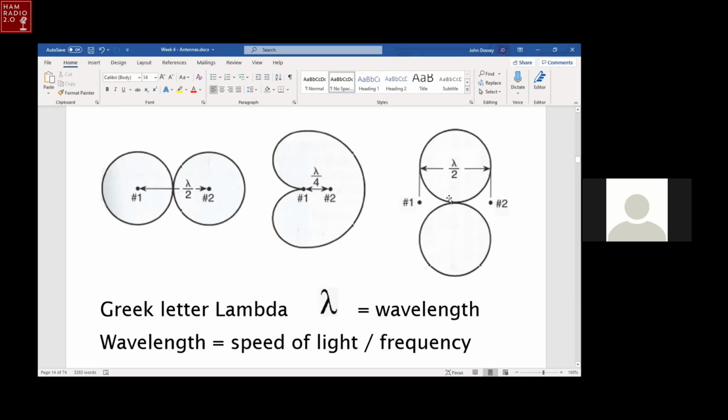You rotated it. In the book, the two vertical antennas are on top or vertical from each other, oriented up and down on the page. I rotated it so that the antennas are the same as 1 and 2 when you feed them out of phase. So I wanted to show that the same vertical antennas at the same position, if you change to feeding in phase, it switches the pattern to broadside instead of off the end.